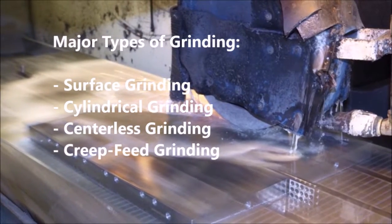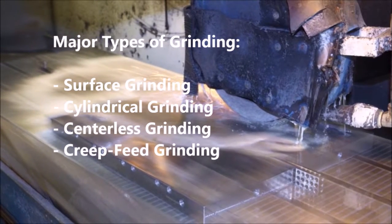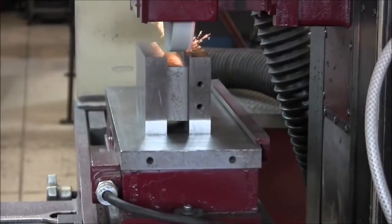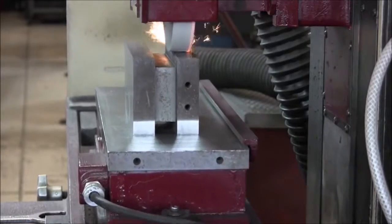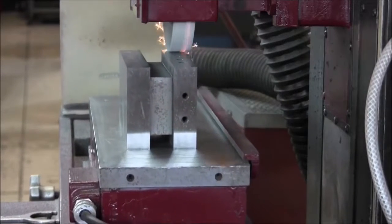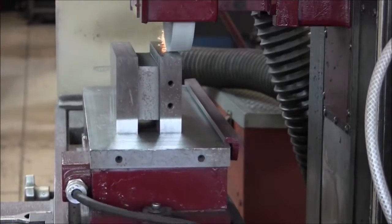Some of the major types of grinding are surface grinding, cylindrical grinding, centerless grinding, and creep feed grinding. Surface grinding is a process in which the workpiece moves relative to the grinding wheel as it removes a small layer of material. This creates a flat, smooth surface. Due to the high amounts of precision and accuracy involved in this process, it is often used when tiny tolerances are needed in the workpiece.